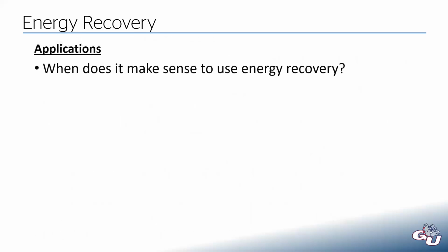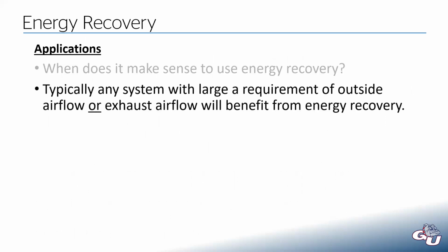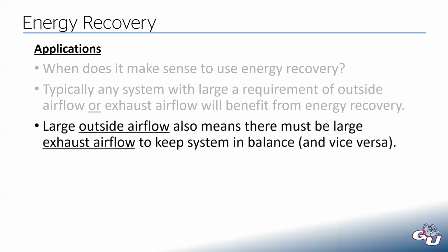So, when does it make sense to use energy recovery? I already kind of touched on this at the beginning, but if you have any system that requires a lot of outside air or a lot of exhaust air, then that system could benefit from an energy recovery system. If you have large outside airflow requirements, that means you have to have large exhaust airflow requirements, and vice versa.